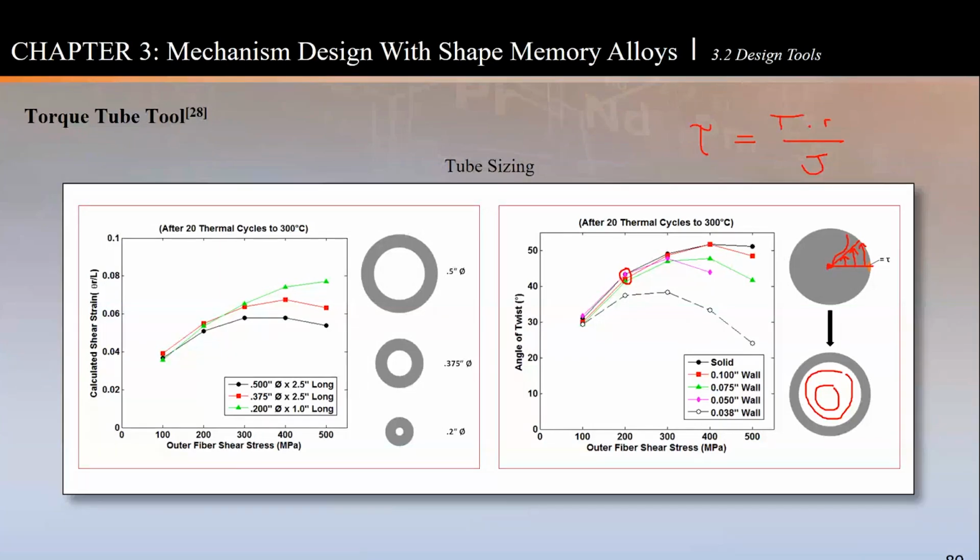And what training implies, you create a path. So imagine when you create a material from scratch, the material can extend, can twist, can bend, do all these things, right? And that's governed by how those martensite twins move. But now if I take this tube and I apply this thermomechanical twist and twist, twist and twist, you create almost like a highway of where the martensite should go. Now the martensite follows the lowest energy state. It looks left and right. I'm just going to go this path.